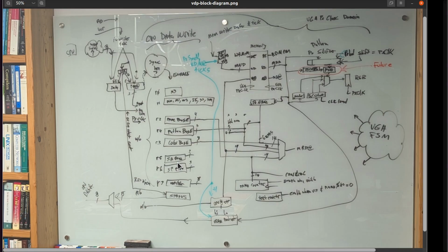So you're going to see a very similar kind of state machine that's used to let the CPU say, here, I want to store some address value into this counter down here, and then subsequently that counter will be used to supply the address. If the CPU wants to read a byte, it'll get it from the address in the counter. Every time it reads a byte, the counter will be advanced by 1 so that it can just keep reading and reading, and it'll just walk through memory and get 1 byte at a time from successive addresses. Same thing is true for writing. It writes down here, and we use the same counter.